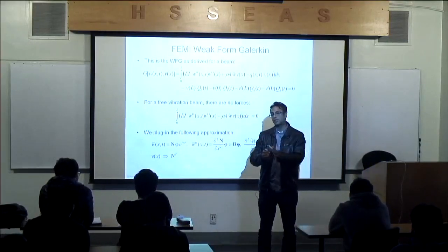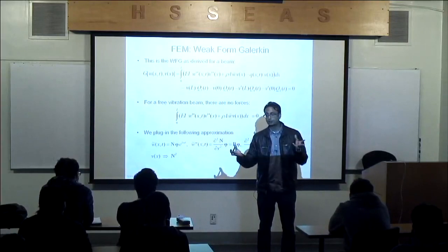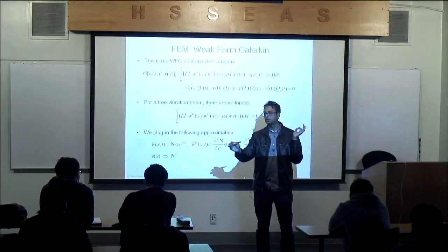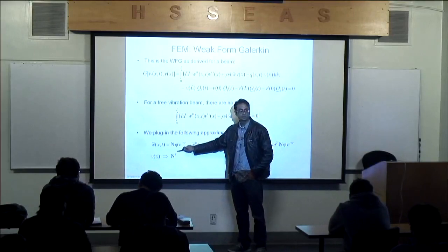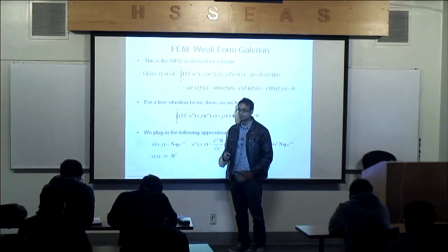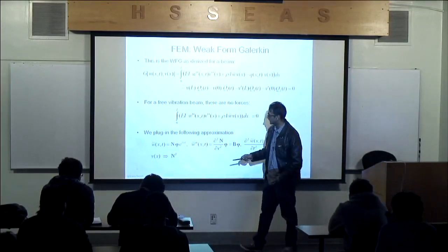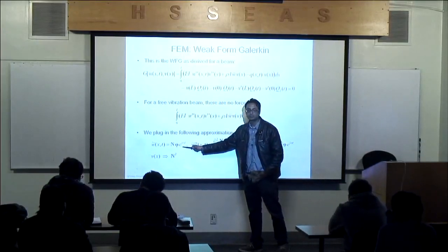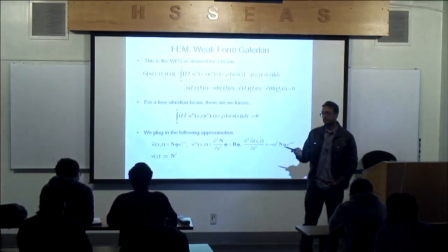Now we could have even more advanced shape functions and more degrees of freedom, like with a middle node. Remember we discussed that you can have a middle node? Well, in that case, I will have 6 values in that vector. But I'm going to use phi, and it will become apparent why I'm using phi as I move along. Times e^(iωt), so I'm going to assume now that the time dependence has been replaced by e^(iωt). This is a little bit different from what we've done before. Okay? It's different from what we've done in the previous lecture.